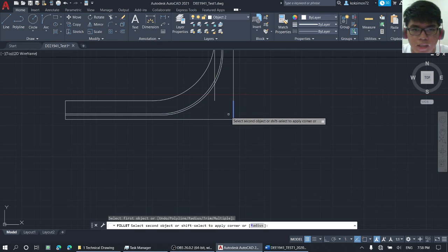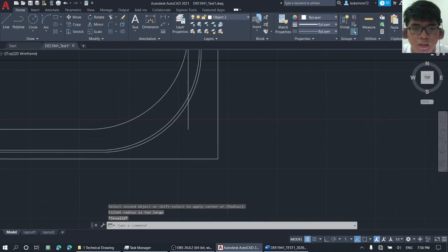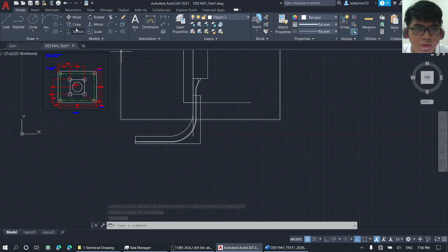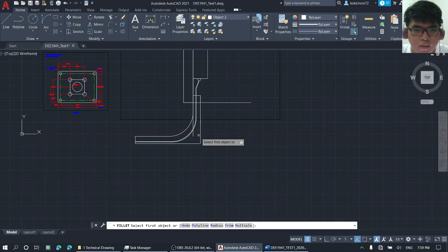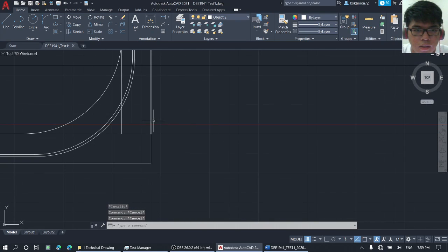Okay, I'll try again. Chamfer. Okay, the problem is that I need to explode it first. Explode, then delete this.